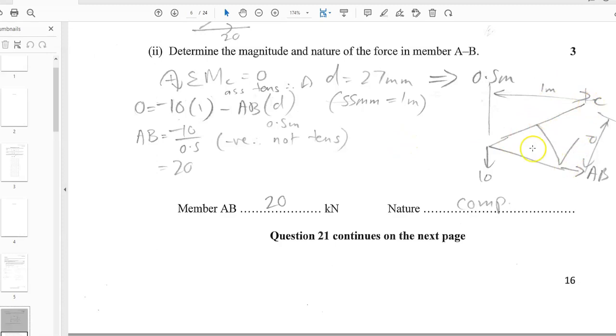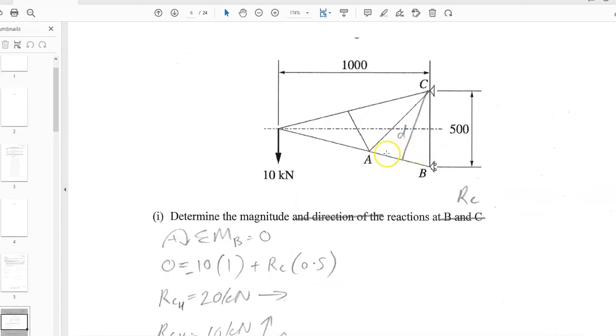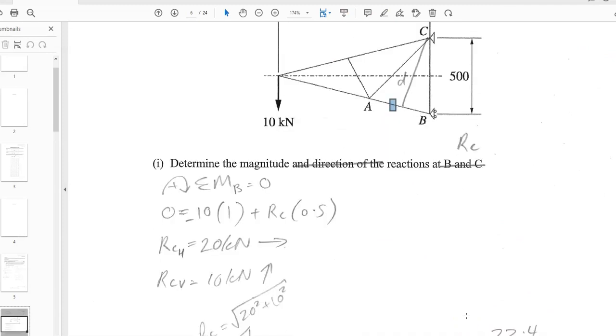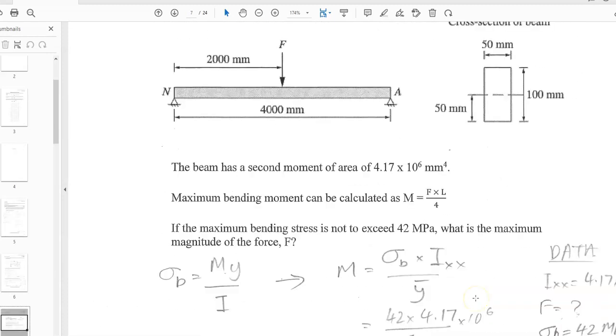We've got that same concept. We've got 10 times 1 versus half times 20. Now, we always assume that the force is pulling out. If we go about C, a force pulling out from A towards B, they're both going anti-clockwise. If they're both going anti-clockwise, it's not going to work. We need one going clockwise, one going anti-clockwise. So the force on AB has to be going in from A to B in order to be going clockwise, right? So if it's going into A, then it's no longer in tension, it's in compression. We'll learn more about that. Year 11 will learn more about that later.